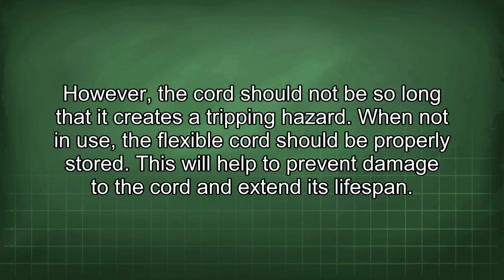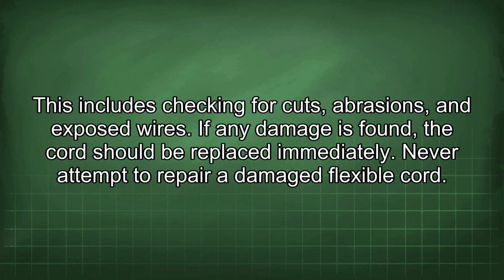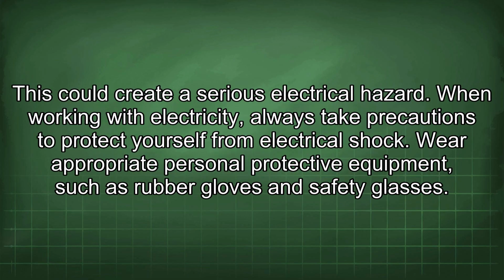When not in use, the flexible cord should be properly stored. This will help to prevent damage to the cord and extend its lifespan. The cord should be coiled loosely and stored in a dry place. It is also important to protect the cord from extreme temperatures. The flexible cord should be inspected regularly for signs of wear and tear. This includes checking for cuts, abrasions, and exposed wires. If any damage is found, the cord should be replaced immediately. Never attempt to repair a damaged flexible cord. This could create a serious electrical hazard.